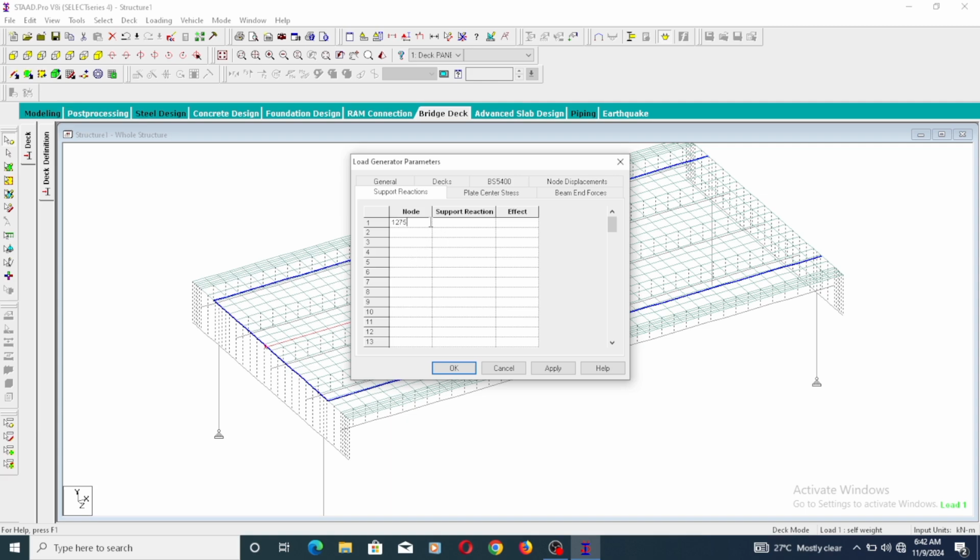So I'll look for the effect also, which is in the y direction, and I'll also look for positive effect. So that's in beam 1010. I'd still like to look at both ends of the beam. I'll type in beam 1010 again and put in the same value. This time go for the other side.